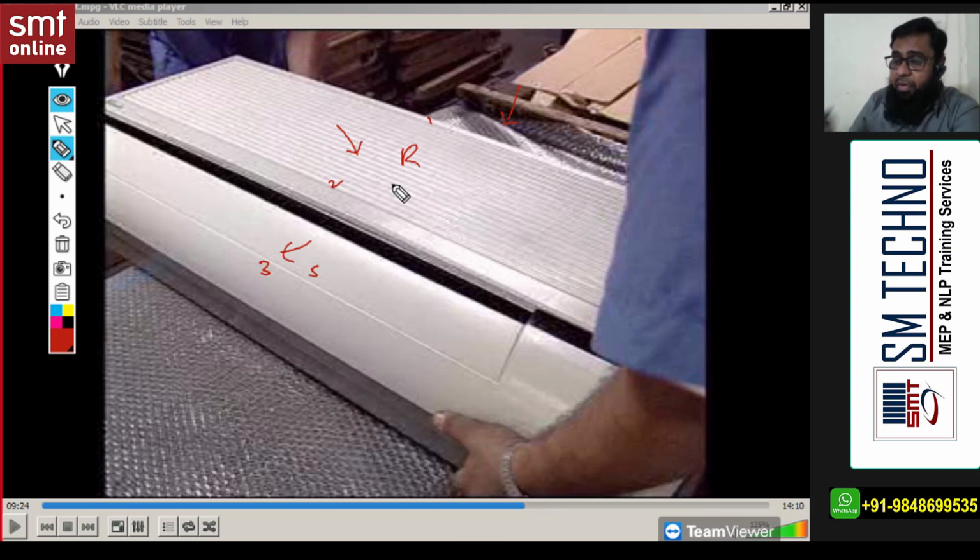Okay. So if you want fresh air, you need to go with a separate unit that we call FAHU, that we'll discuss later. Whenever suction takes place, in the panel you'll find the filter, and you'll find the filter in this window panel also. Normally plastic screens, because a plastic screen is not a standard filter, but in window and split units you'll generally find plastic screens. If you talk about a ductable unit, you'll find the standard fibrous filter. But at present this is a normal plastic screen.